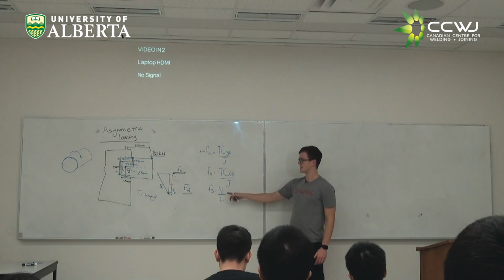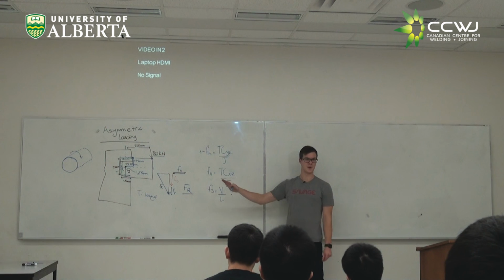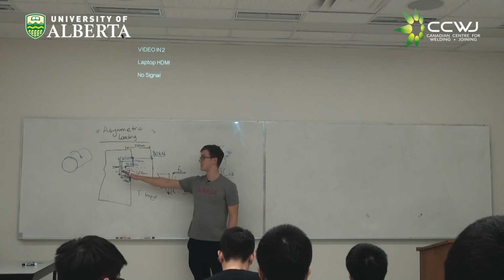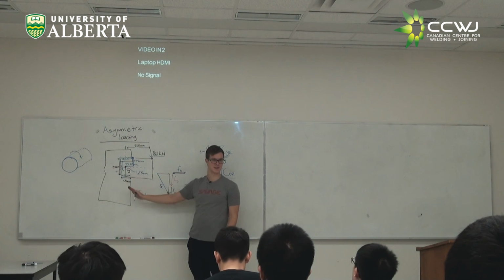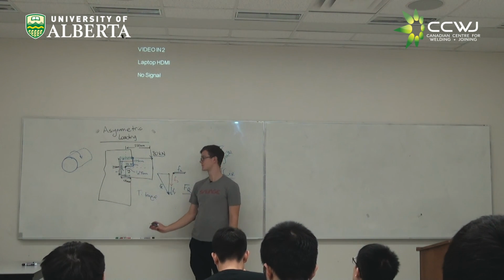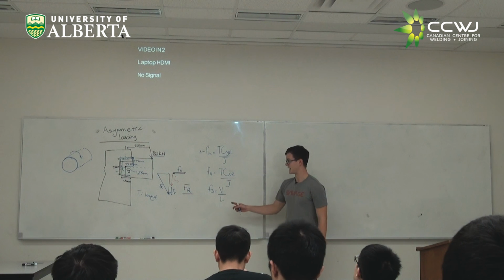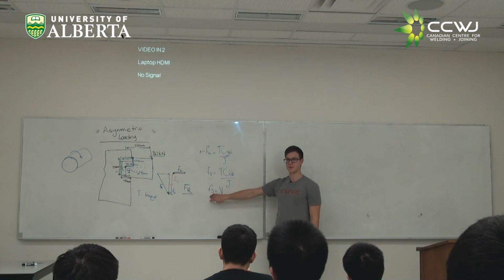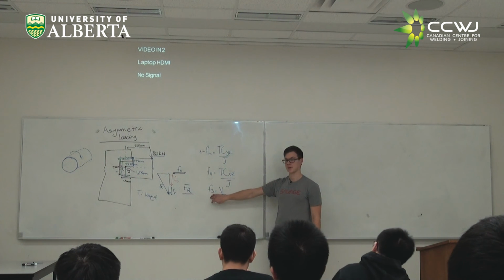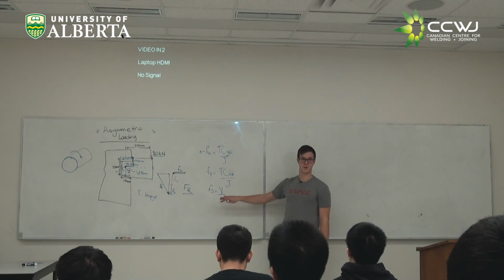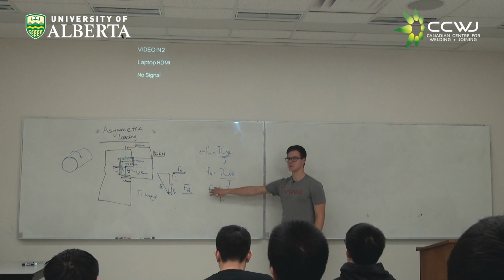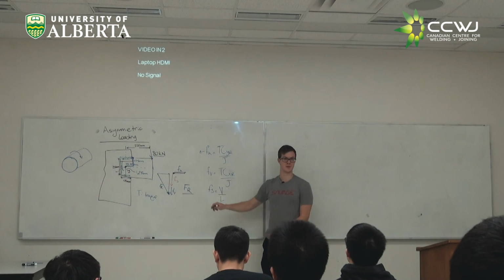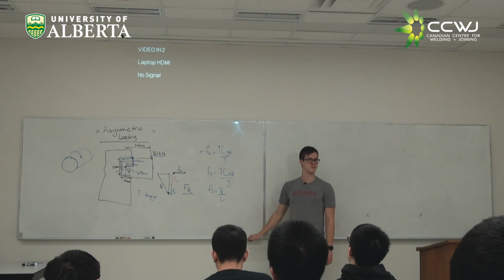So this ends up being a similar problem to the first problem. If you ignore all of the off-axis, you could solve the problem of this 80 kilonewtons passing through here, right? And it ends up being the same situation where you solve for this FS. If you have that FS, you could solve for your weld size, but before we solve for a weld size based on the FS, we have to first consider other load situations.